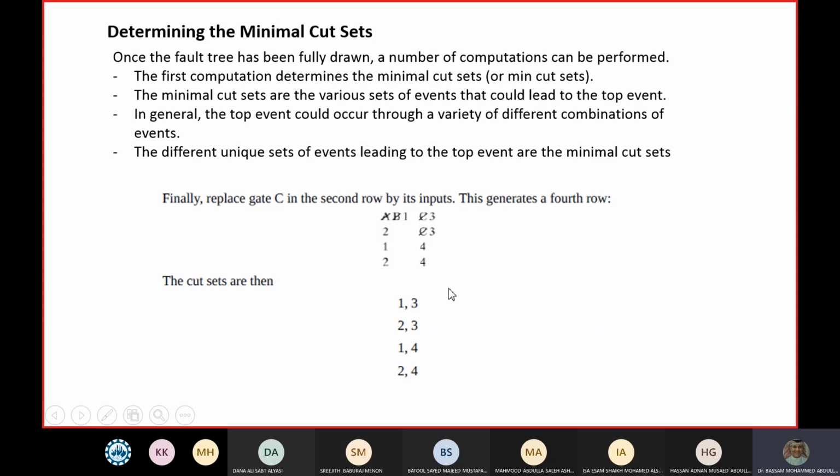So we are going to calculate for all the cut sets that we already found that they are possible. These are the possible cut sets to have an overpressure. And then the one with the highest probability of failure tells me that, for example, I'll tell you which one is the highest, and you can do the calculation. 1 and 4 is the highest, which is 0.044. Actually, 0.044 is still low, but it is higher than the rest.